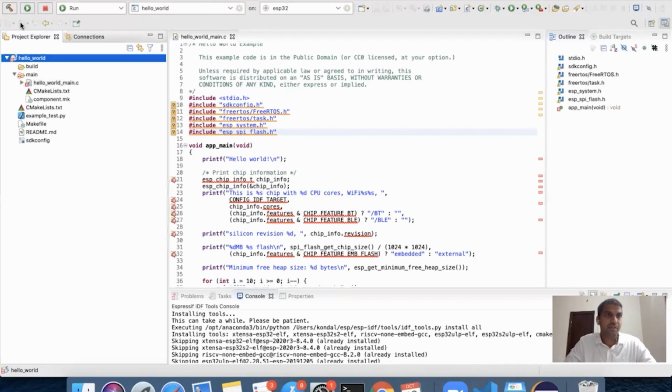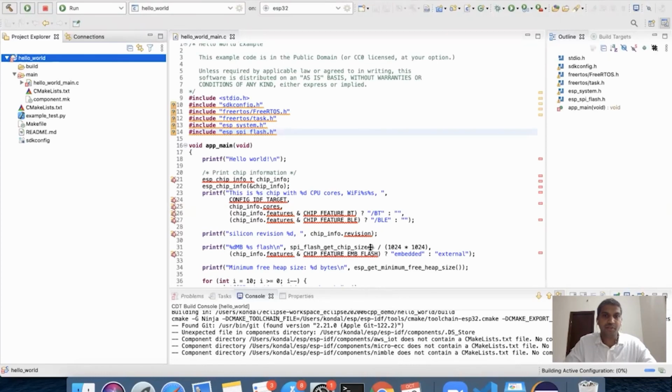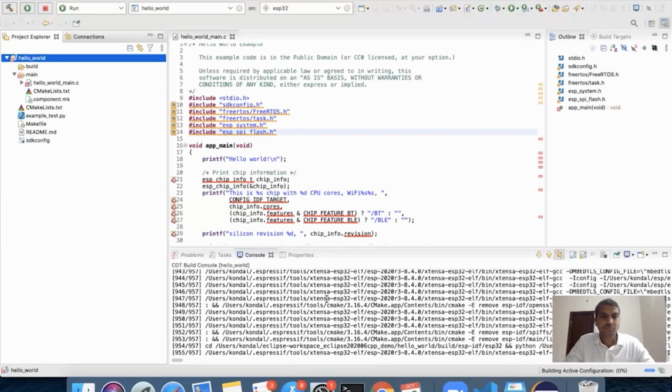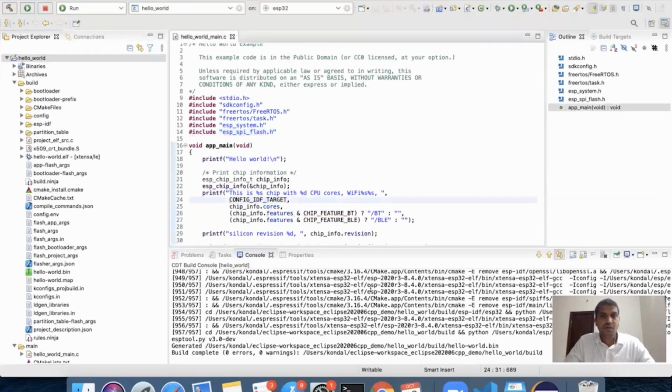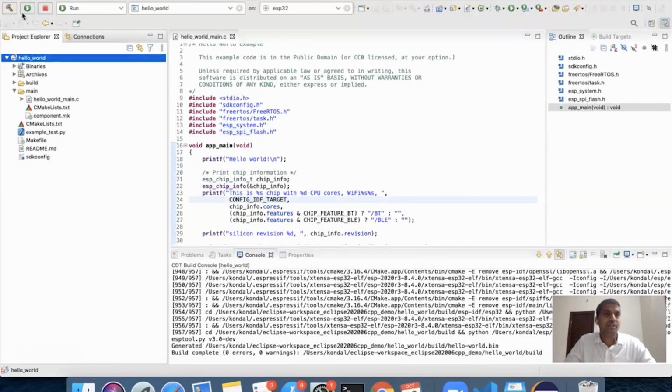Fine, you can just go ahead and click on build. So this is going to take a couple of seconds. Awesome. So the build is completed. As you could see, the moment the build is completed, all the errors got resolved for your project. So the next thing is, this icon represents a build, and the next icon next to this build icon represents a flash.